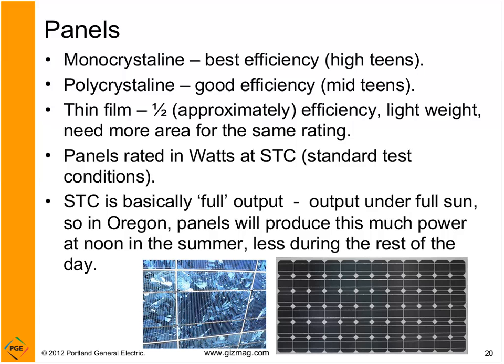For you folks in maintenance and facilities, the warranty on panels is typically now 20 years or more. There is a degradation percentage built into that warranty, but fundamentally you should plan on your system being active and running for at least 20 years. There's been a lot of history on some of the very first panels built, and one of the reasons we don't know how long we can say these things last is because they're still up and operating, even though some of them were built in the 60s and 70s. So they last a very long time.